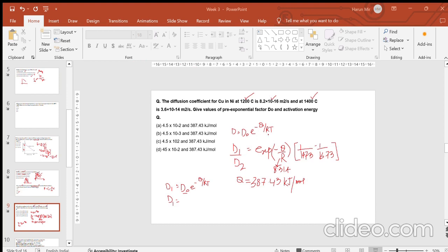You know R, and T is also given because you are given a temperature of carburization, which is 870 degrees Celsius. Just plug in your values and find the value of D first. Then we will do the actual part. So first we have to find D. Okay, so if you can find D, then we can move to the main part.